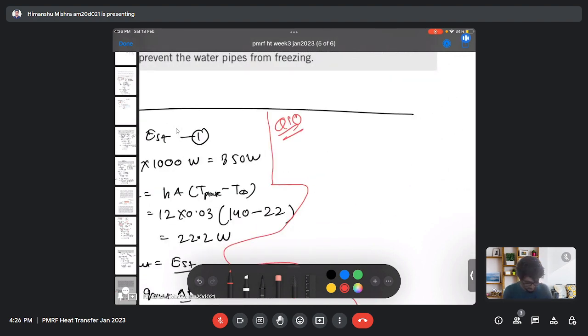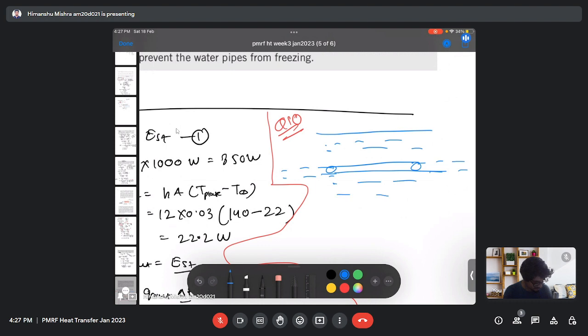So in this question we have, let's say, a ground we have given. We have an infinite pipe, and this is the ground. My surface temperature is minus 10 degrees Celsius, and there is water in the pipe just flowing down. So we will solve this question by not using the lumped heat transfer. We will solve this problem as a long body problem.